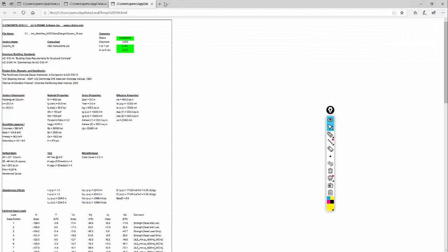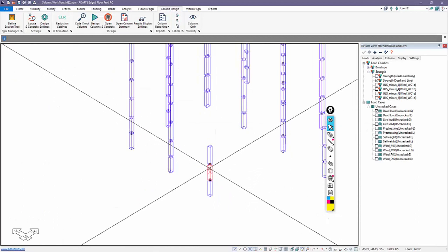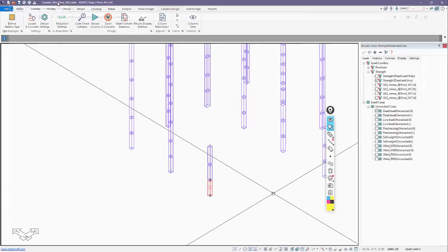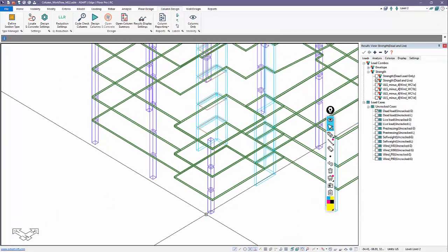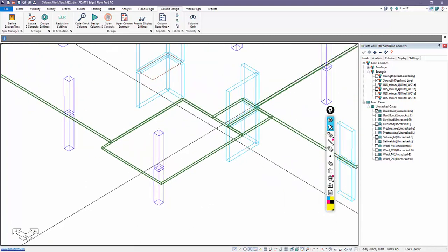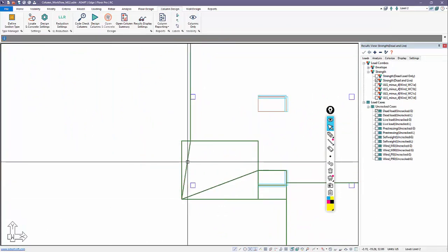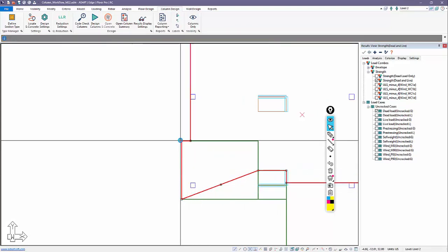That's shown here. We should have actually adjusted that lower slab because the program sees that that slab is offset and it runs the length down to the bottom. So this one will be 112. If we look at the unbraced length here, this will be, or excuse me, 112. We have an 8-inch slab at that location. So let's go ahead and make the second modification to fix that lower slab. Select this, move this over, and we're going to insert that point 1 and 2 again, and then adjust the slab.